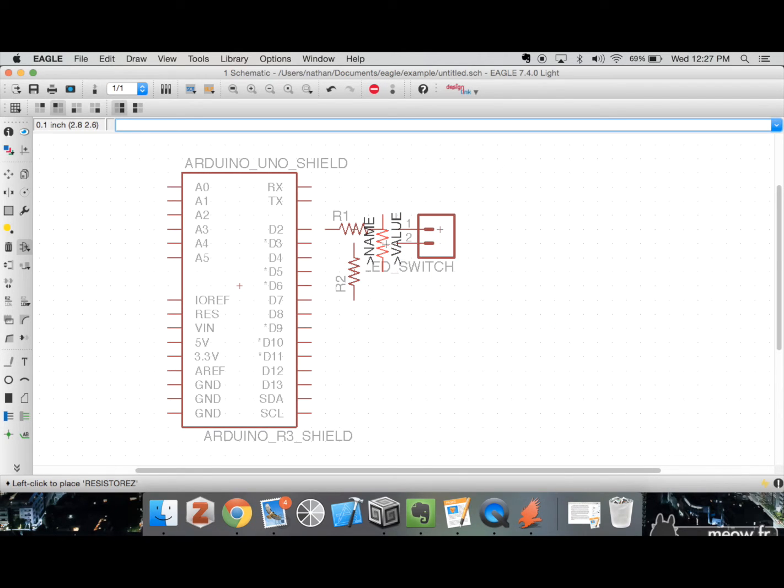Now, what if I want to move my switch a little bit closer to these resistors? I do that by using the move tool. Of course I can click on all these icons in the panel here to the left, but it's much easier and you'll end up liking Eagle more if you just type in move instead. So I'm going to do that. There's my verb. My noun is the switch. So I click on it, and then I'll just move it 2 clicks over. All right, excellent.